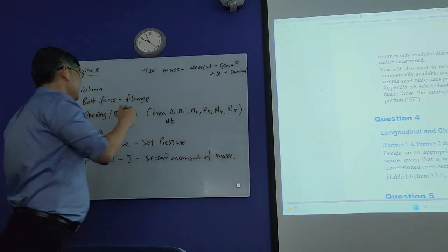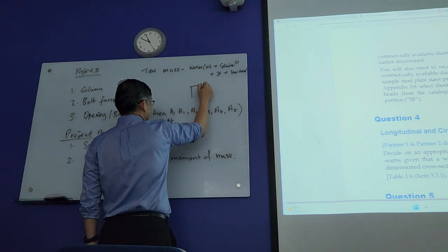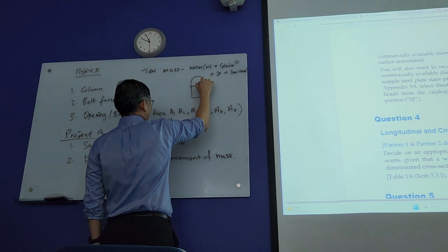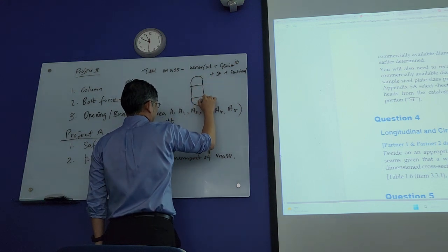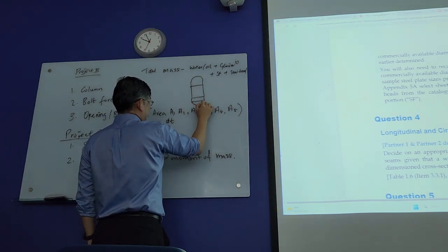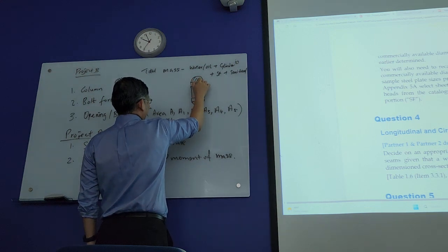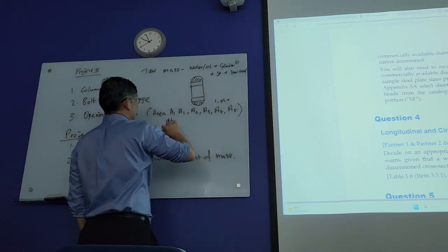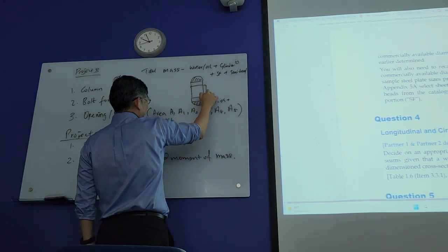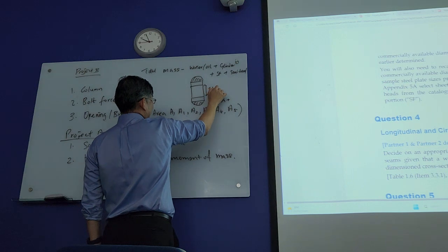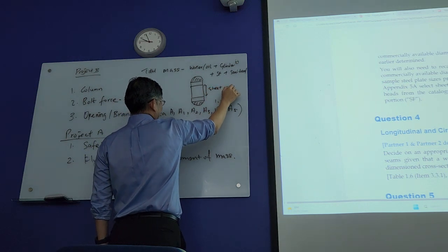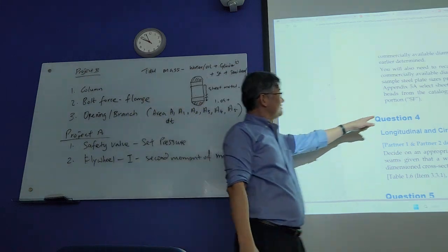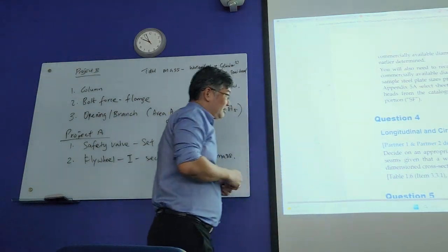I should say exclude. That means this is your cylinder, and then this is your semi-ellipsoidal head from the vendor, right? So this part, apply the formula 1.09 something just now. Cylinder, your sheet metal, and then this part you have to include. This part is from your catalog.